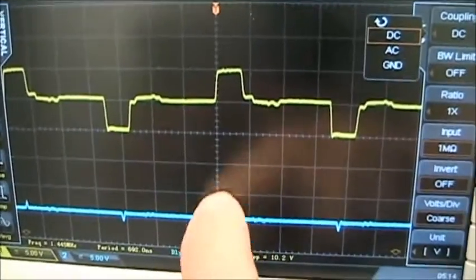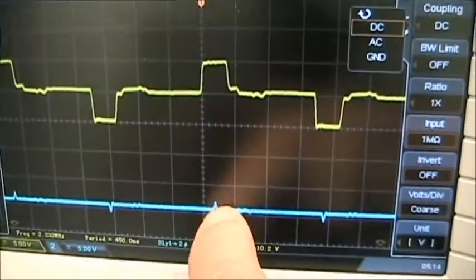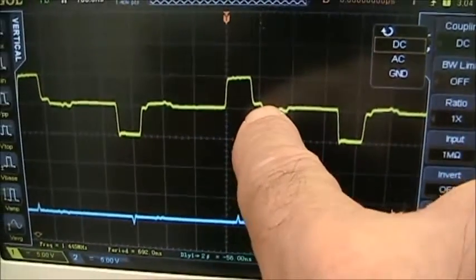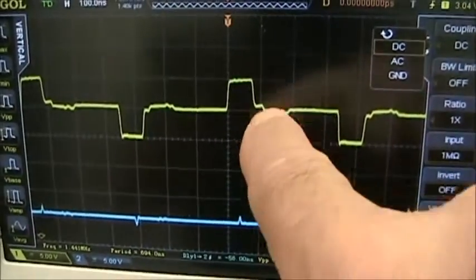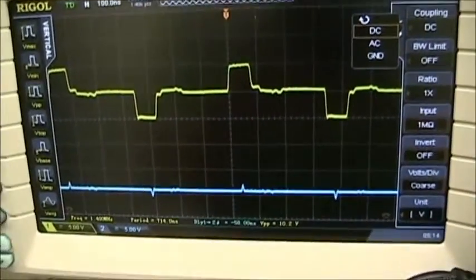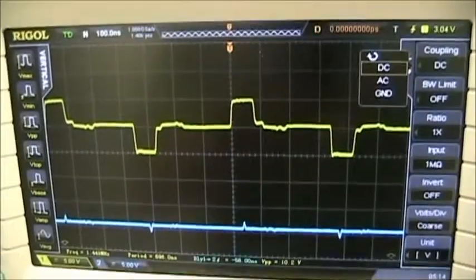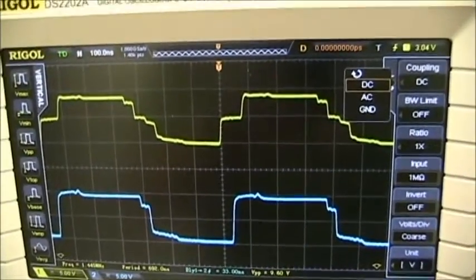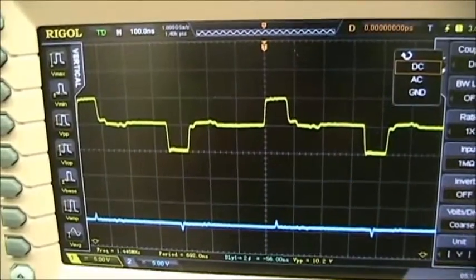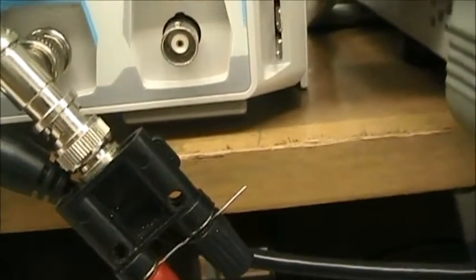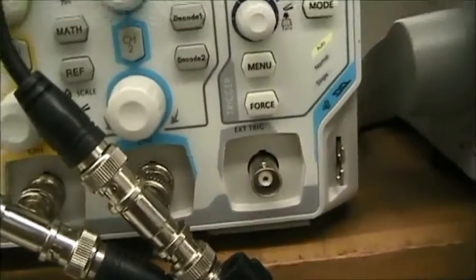And that is because the input pulse travels down to the load where it is reflected negatively. That negative pulse comes back and cancels out the input voltage. We'll see that in better effect later in the lab, but that is the effect of a short on a line. The voltage goes to 0. So open and then the short. If you want to, you can experiment with the short itself. You can make a longer wire for a short, and that will change the look of the signal.